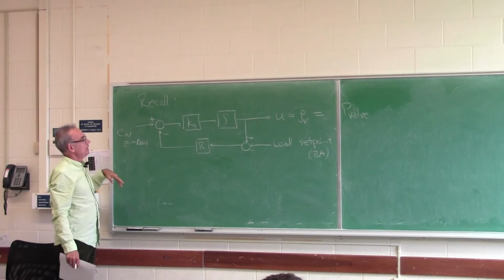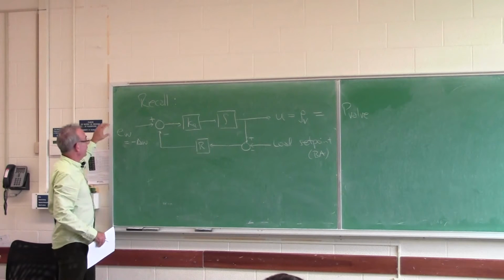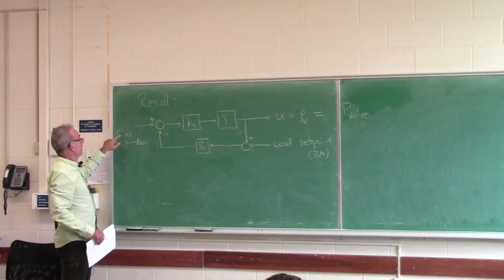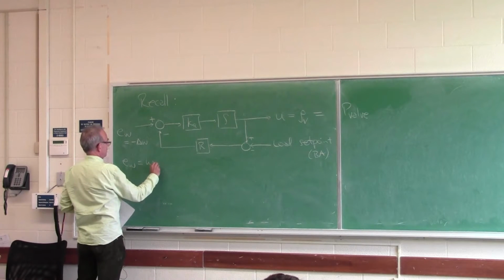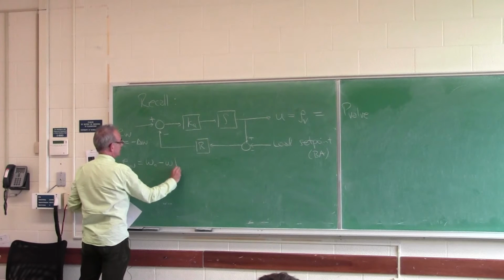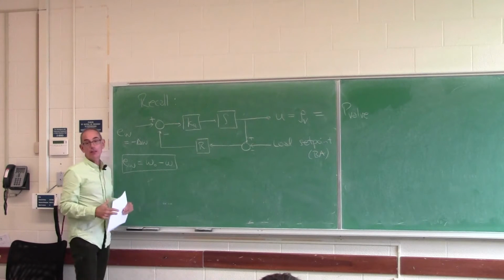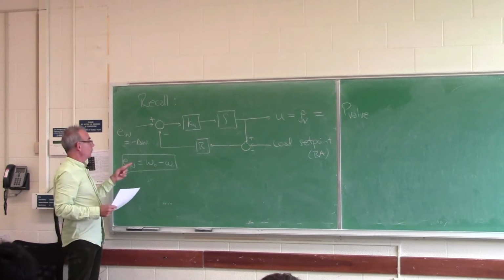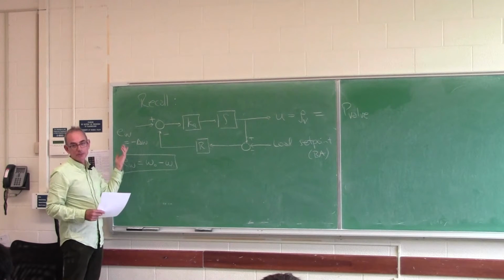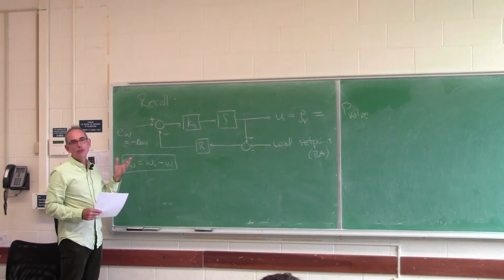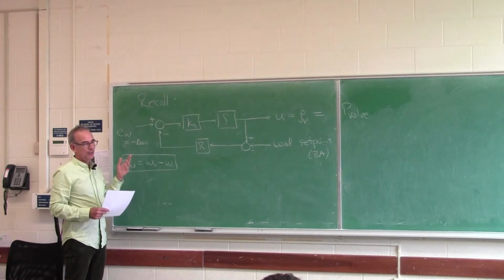Normally you take an error signal, E, which is defined as what you want minus what you've got. So in control, that's the typical notation. But the definition of delta omega is the opposite. So that's why the control loops look really funky in the book, if you're a control person.